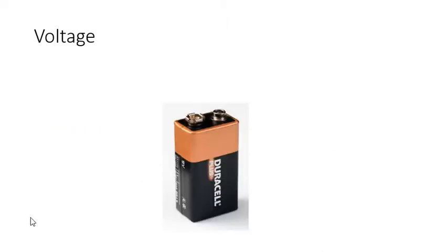All right, so let's look at a battery. So I have a picture here of a 9-volt battery. This is just your standard 9-volt battery. Well, what's that mean then if it's a 9-volt battery? Well, first of all, it's 9 joules per coulomb is our voltage, which means between 2 points, there is a loss of 9 joules of energy for every coulomb of charge that leaves this battery.